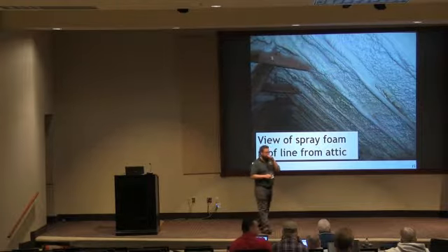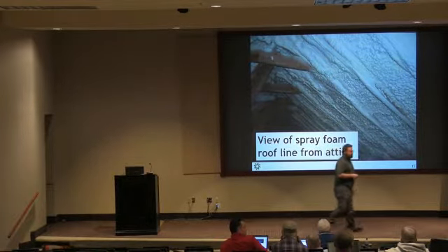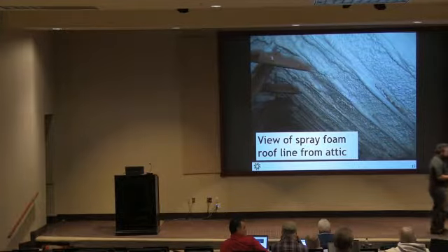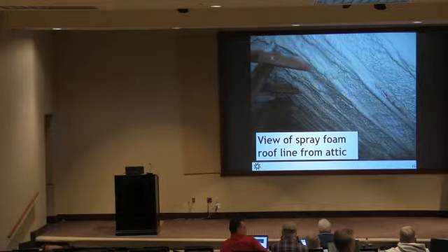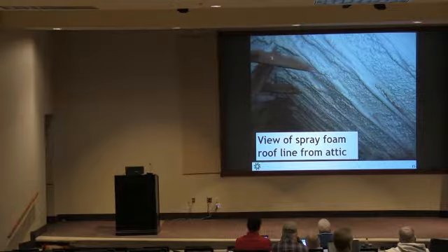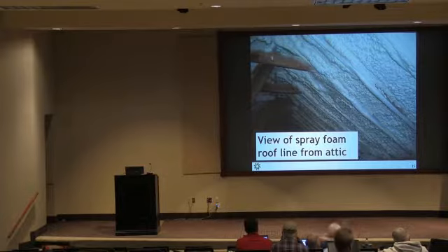Yep. I believe the building code states that if the attic is used for storage, you have to be concerned with combustible items. And the closed cell, it's labeled, I believe, so you don't have to have anything over it. This is a situation with the open cell. Interesting question. It really depends on the manufacturer of the foam, because some mix fire suppression into their product. I'm not a chemist, so I don't know exactly how that works, but you can get a product that is rated essentially to be fire safe. Other products need to be coated with an intumescent coating that comes on afterwards.